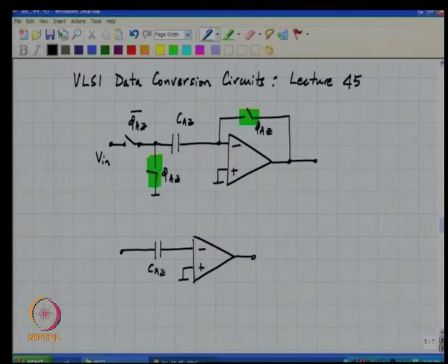As we saw the last time around, the input of the preamplifier itself has some parasitic capacitance Cp, and we saw that it makes sense to choose CAZ to be not so small as to cause a big attenuation due to the series combination of Cp and CAZ.